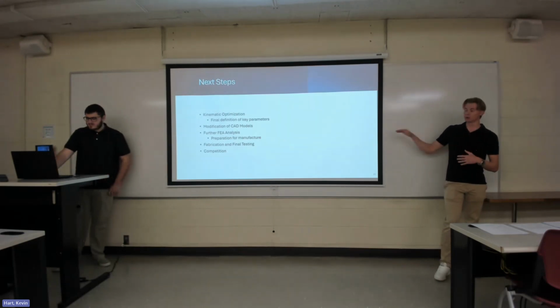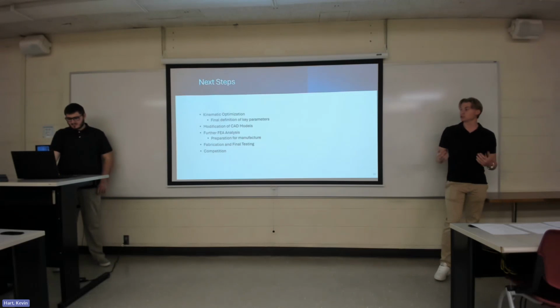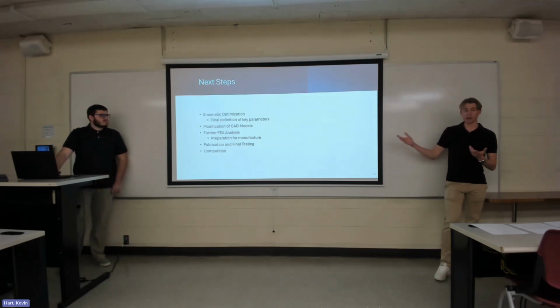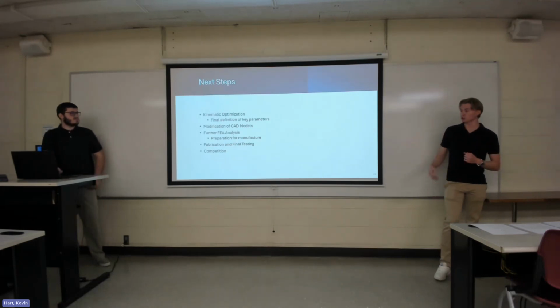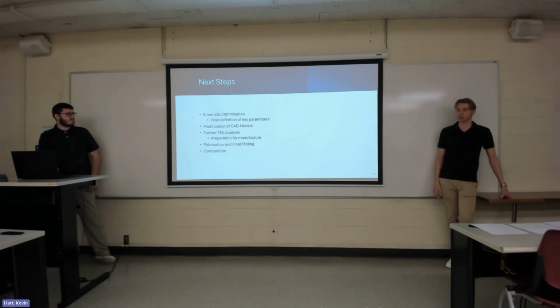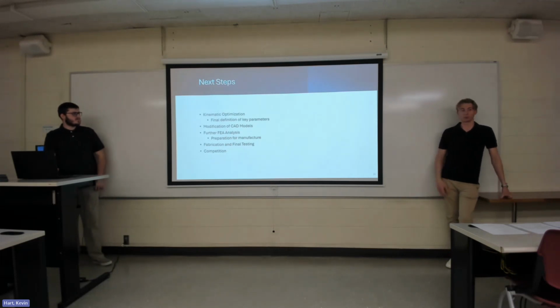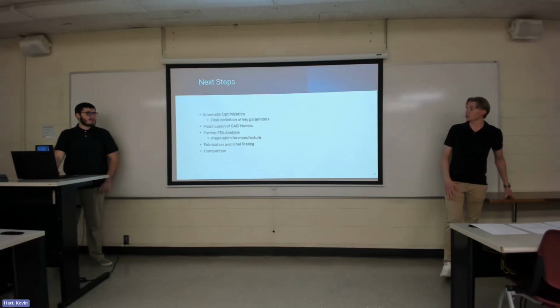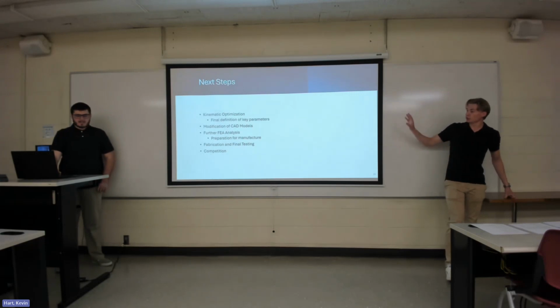And then we'll be able to run a more refined FEA analysis that's going to more accurately model our actual load cases that we're going to be running through. Since those dimensions are going to be changed, those load paths are going to be slightly different as well. So that's going to potentially bring up new areas that we're going to be interested in strengthening or refining through that FEA analysis. And once we're done with that, we'll be able to manufacture and put it on the car in May.